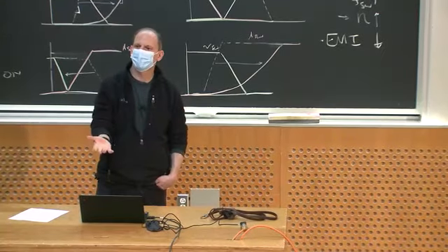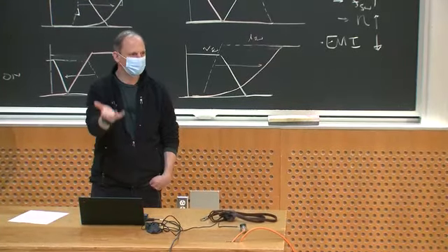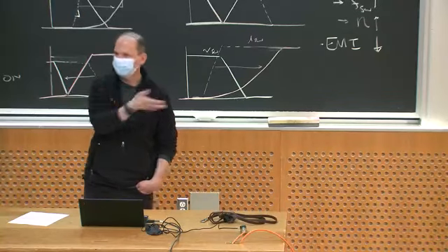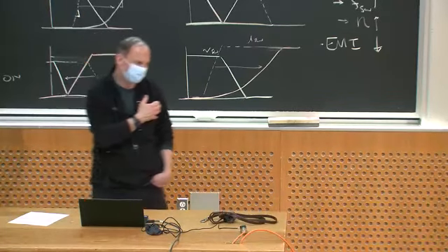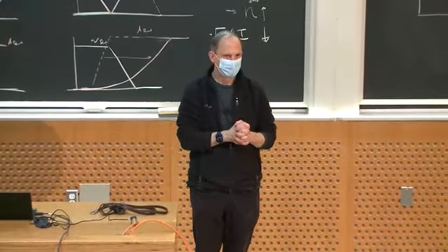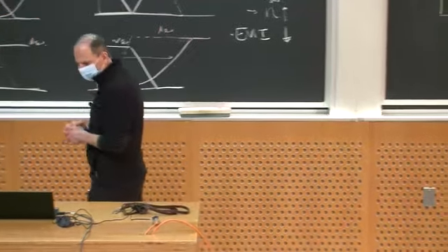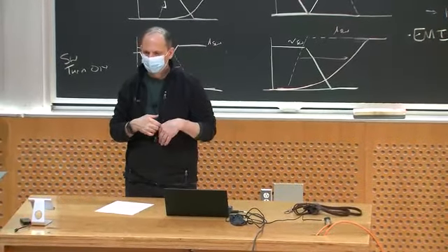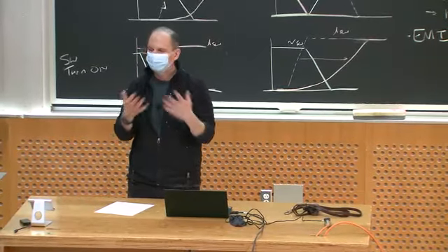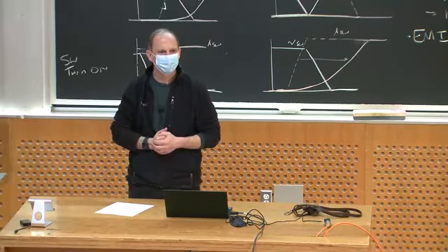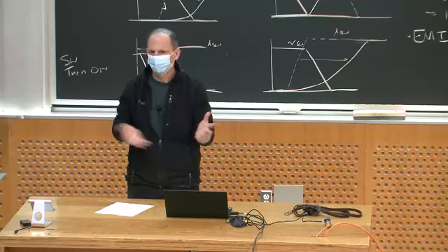This circuit works under variable switching frequency and variable duty ratio based on hysteretic current control. So everything about it is governed by the desire to get soft switching. So if I told you, you know what, we want to do harmonic elimination PWM with this inverter leg, can you do that? Not really, right? You don't really have the means to do it.